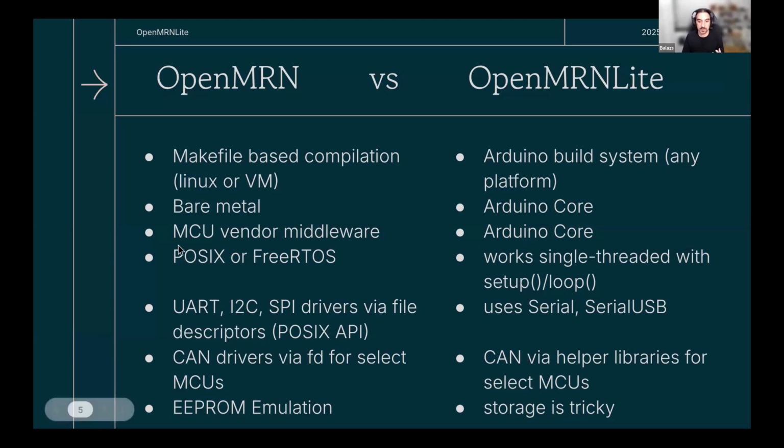Also, when we are looking at basic drivers, talking to a serial port, etc., all of that we are usually doing with the vendor middleware from whatever microcontroller is being used. So for, let's say, a Texas Instruments microcontroller, we use the TI middleware, TivaWare, or the SDK for the MSPM0. From STM32, there is also the STM32Cube middleware layer, etc. Every vendor basically provides their own middleware.